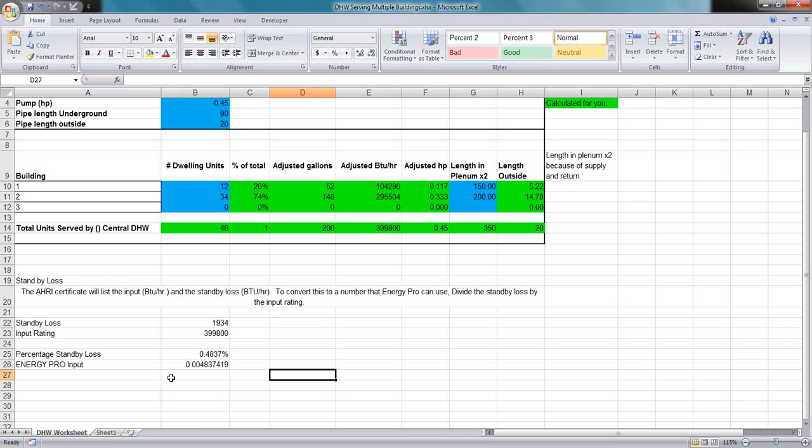You know, if you can't get a brake horsepower and you need to do a draw, then tell the maintenance guy that you're going to be leaving some equipment there for a week to find out what the operating conditions are of that pump. And obviously, just like everything else, document it, photo, write it up, make sure your program administrators are on board with how you're capturing that information. But I wouldn't recommend just doing a one-time draw and assuming that's the brake horsepower of the equipment.